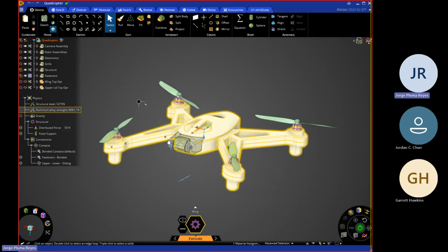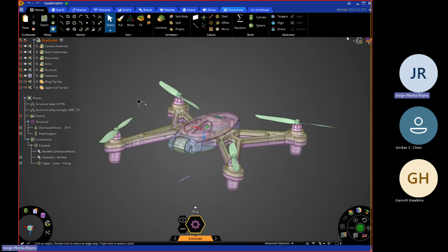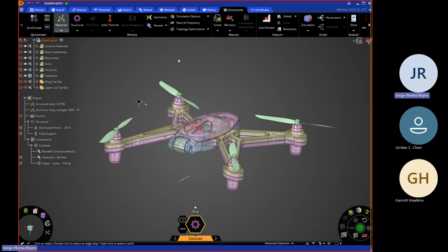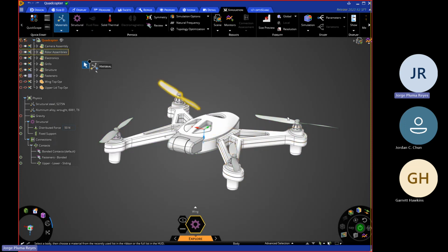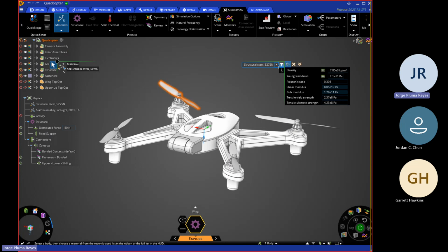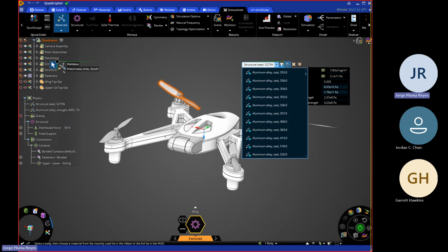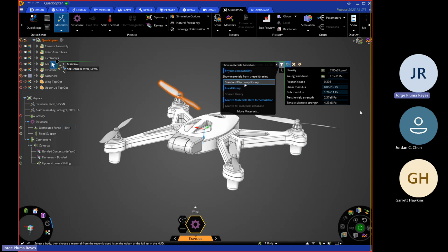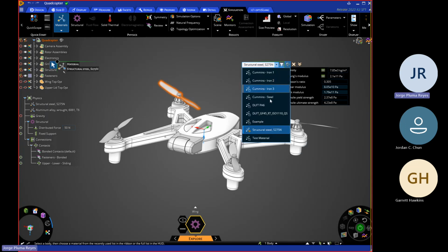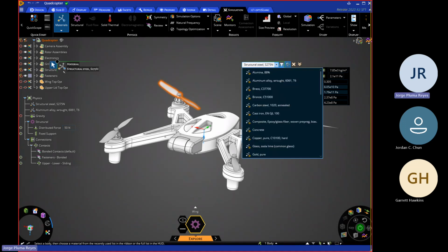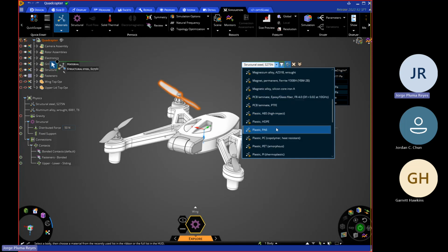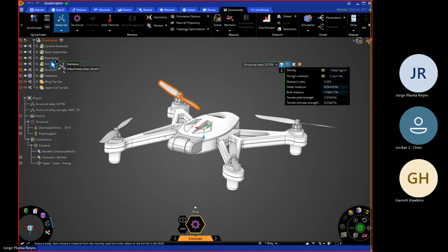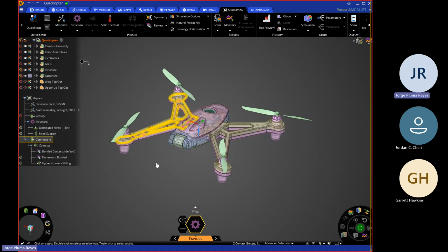So what I did was assign my materials. I think I didn't mention that, but in the simulation tab, you can assign materials. You just click on materials, then click on your part and give it whatever material you choose. I have an extended version, but the local library is still pretty well stacked. For example, you'll be able to see brass, bronze, laminates, plastics, and so on. But yeah, this is already pre-designed with materials. We have a simpler model here.